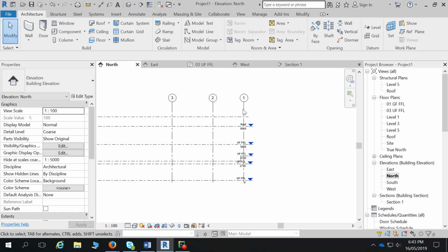You don't have to remember to change the spacing if the structural engineer said, oh, we need 5-meter spacings for whatever reason. So grids again is pretty easy. You'll notice as well with the levels, if you delete one, it'll just keep going up in number. It won't go back and renumber something that you've missed or deleted.